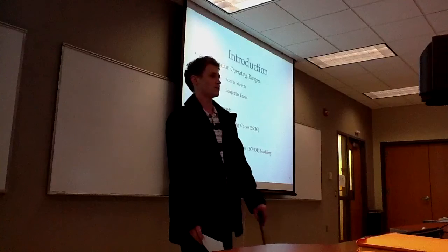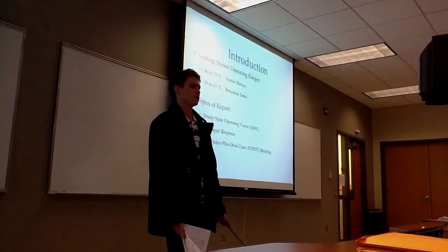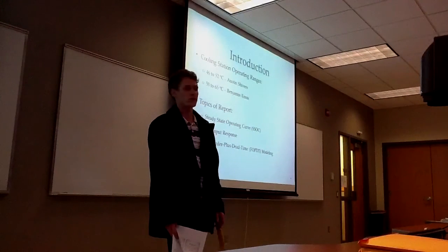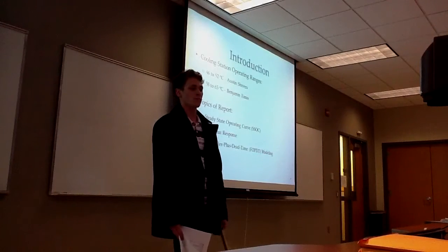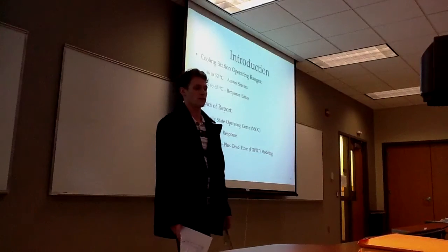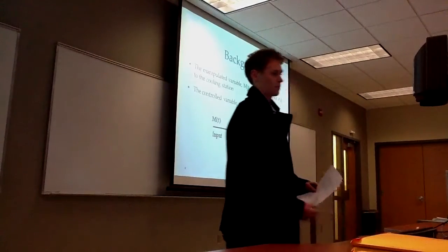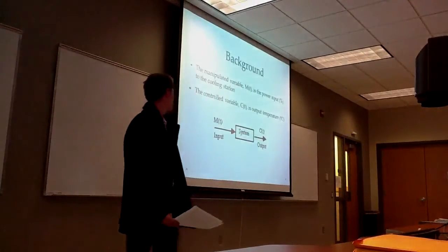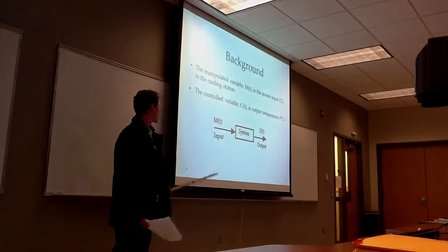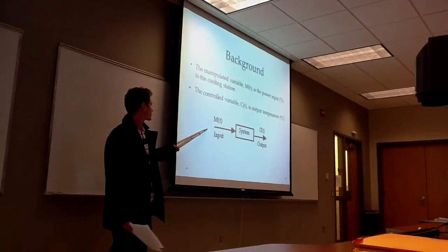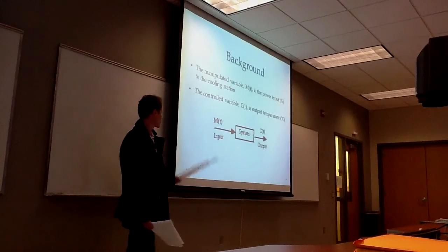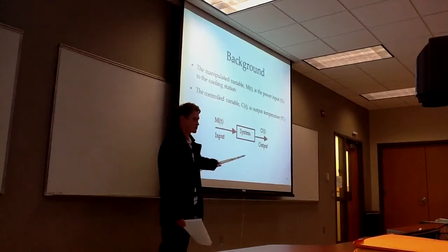Today I'm going to be reporting on our steady-state operating curve, the step response, and the FOPDT modeling. For our system, we have a manipulated variable, which is just the input power to the system, and our control variable is the output temperature of the system.